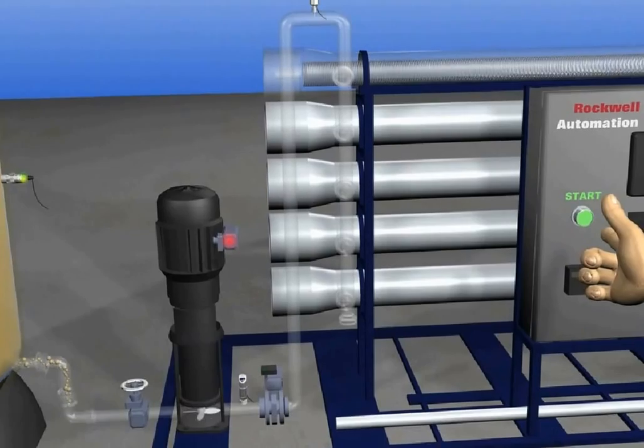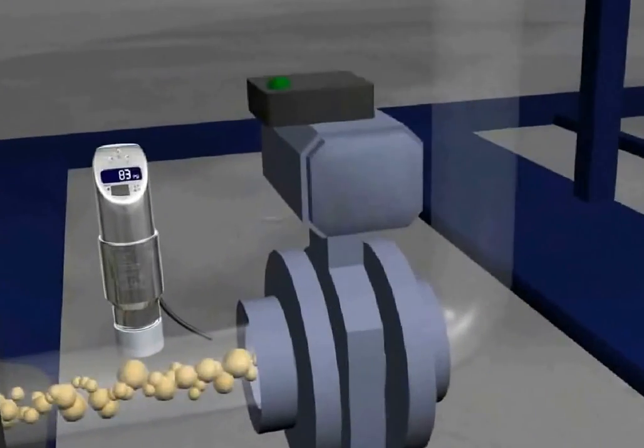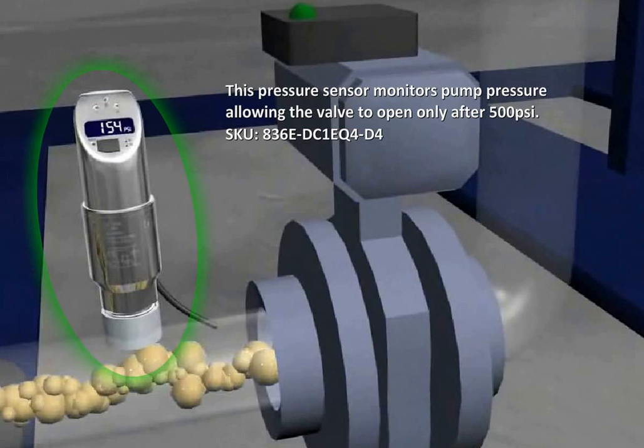Once the process is started, flow passes through the high pressure pump, where a higher feed pressure of 500 psi is created for the feed water. We are using an 836E display pressure sensor to check the feed water pressure. The 836E device is made of 316L stainless steel. It can be programmed using push buttons or PC software. Also, it is available in switch and 4 to 20 milliamps analog output versions.